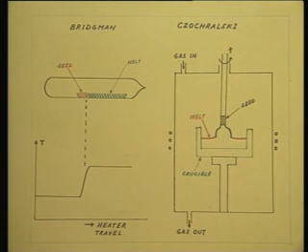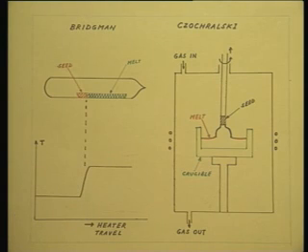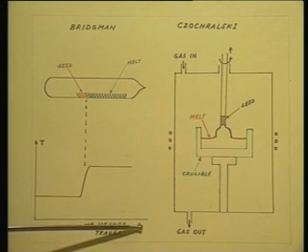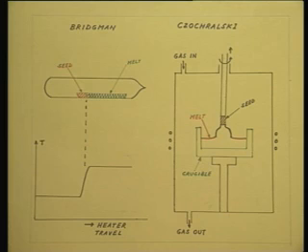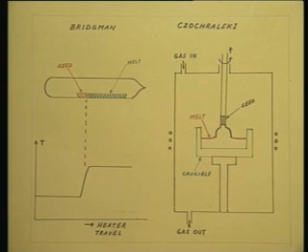Therefore, the temperature profile of the furnace has to be something like this. Temperature versus X. So, you see the seed end is kept at a lower temperature, while the charge, the melt, is at high temperature, and therefore, it is in the molten condition.